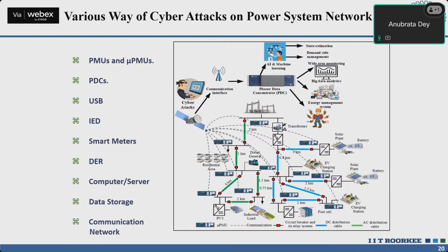Discom using two-part tariff. As we are paying the bills, we have the block rate tariff, where we have the number of units consumed multiplied by the rate. There the company has the two-part tariff. They have this running cost, how many units they have consumed, plus some fixed cost. The fixed cost is calculated based on the contract demand. They call it contract demand.